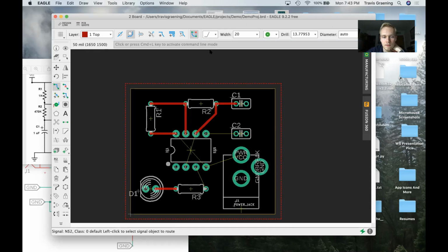Edit schematic after getting rid of ground wires. Well, the thing is, it actually doesn't get rid of the ground wires. We still got all those connections made. The connections are just made under the hood for us because we've got the entire ground plane. So each of these is still connected to ground. So yeah, the schematic hasn't changed. All the same connections are being made. We just don't have to manually route it ourselves because there's a trace doing that job for us.